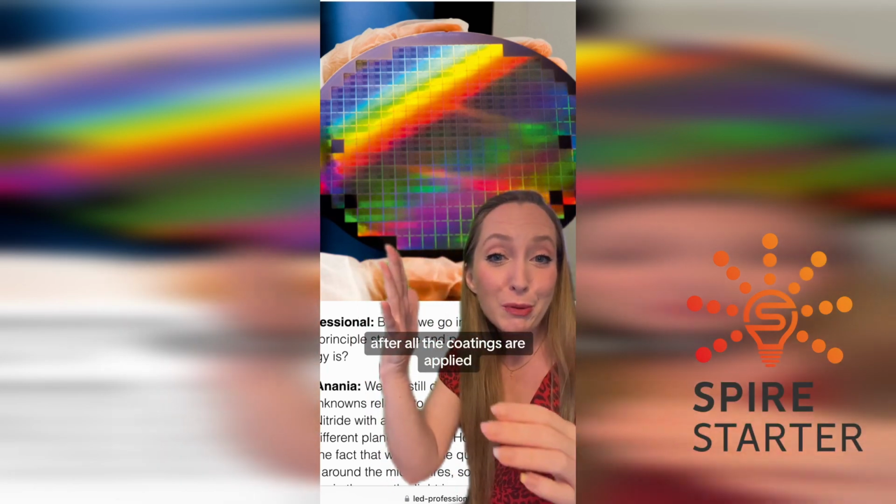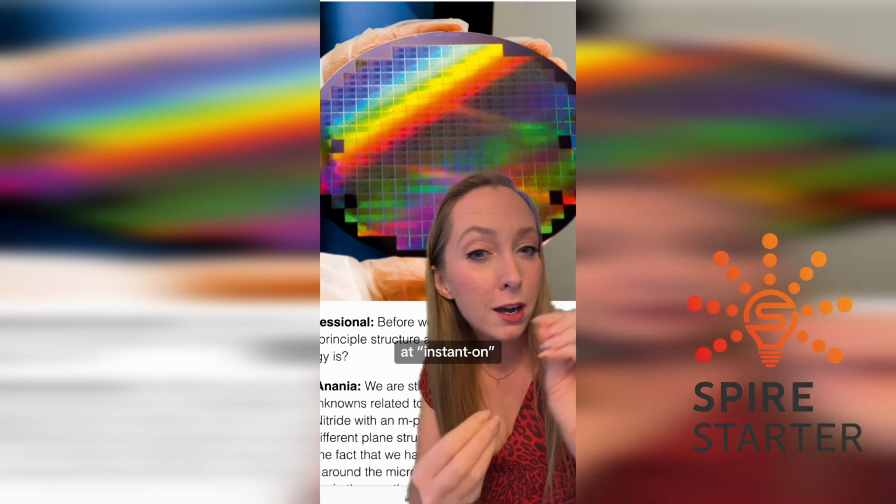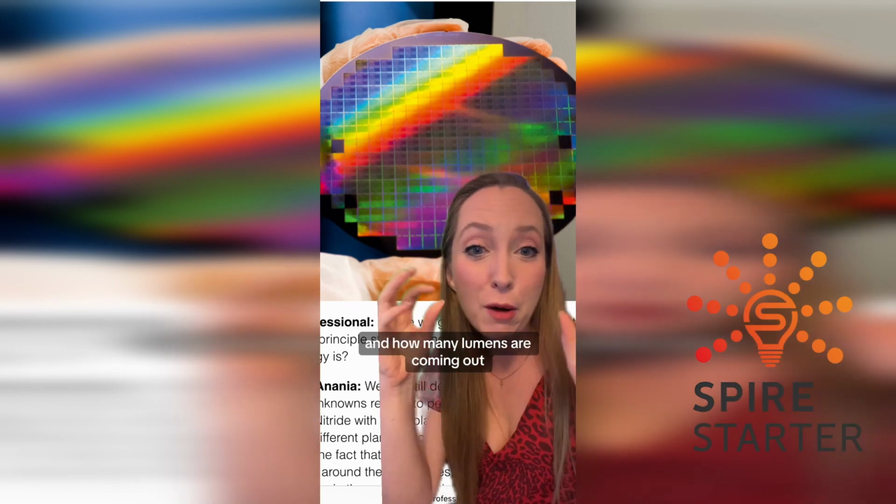So after all the coatings are applied, these things are diced up, and then each one is individually packaged into like a fully functioning LED diode, and then they're flashed on and instant on to measure the color temperature, the CRI, and how many lumens are coming out.